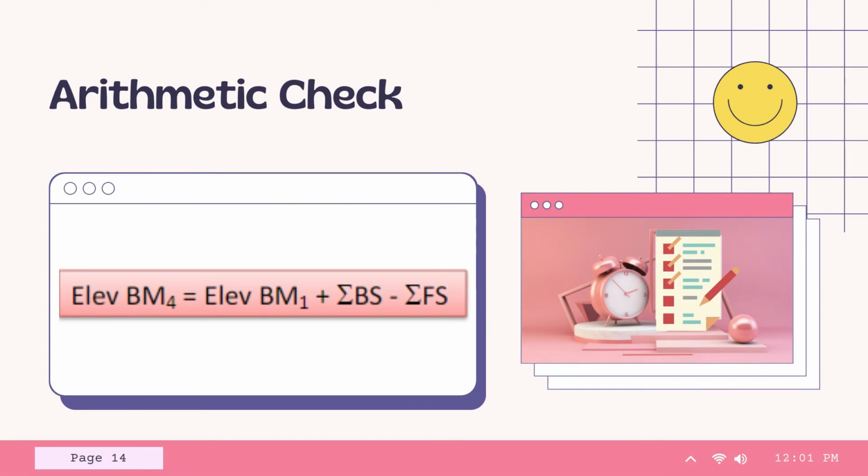Before trying the simulator, let us first look into the formula for arithmetic check. This formula is essential to determine if you have some errors in your calculations while doing the differential leveling. Here, the elevation of benchmark 4, or the last benchmark, is equal to the elevation of the first benchmark plus the summation of the backsight readings minus the summation of the foresight readings. We can check that later in our simulation.